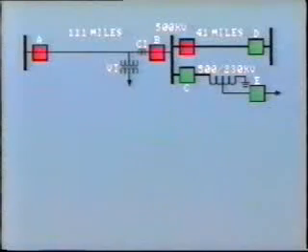You can see that oscillogram recordings such as these are quite valuable to engineers and others concerned with investigating a disturbance. They provide us with documented evidence of the disturbance and allow us to determine if the protection has operated as planned. Let's now move on to our final case study, case 6, transformer energization. Here, we'll show how an oscillogram analysis can help improve switching procedures for system dispatchers.